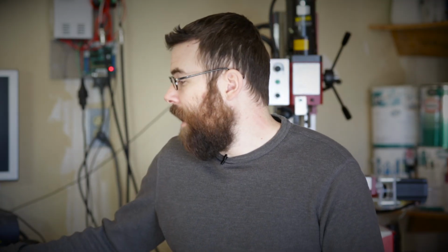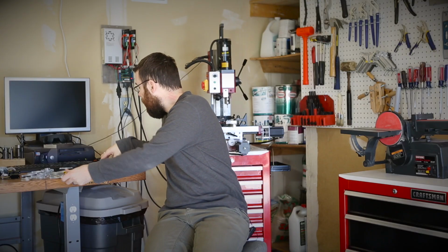Another main difference between a pulley and a sprocket is of course the lack of teeth, and that means that the power transfer is going to be a little bit different. A chain is not going to have a lot of slack and not a lot of give. I mean, it's going to be negligible. However, with a rubber belt such as this, it's going to have a lot of slack and a lot of give. Now, for certain applications, that actually might be desirable, but ultimately what that means is a belt like this is not going to have quite as much power transfer to it, and it's not going to be as good for higher torque applications.